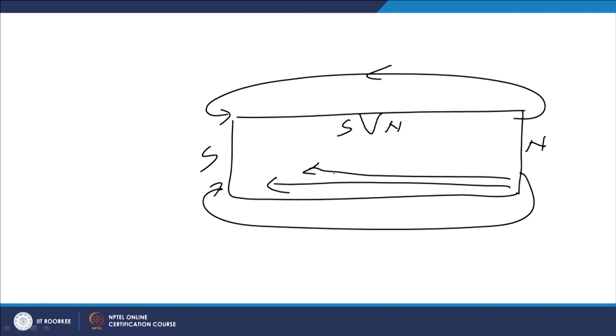But if there is a pore or a crack, then again it will form 2 poles, and wherever the defects and discontinuities are present, leakage of the magnetic flux starts from that area. This leakage of the magnetic flux will lead to the formation of additional fields here, and this aspect is exploited to detect the locations wherever the discontinuities are present.